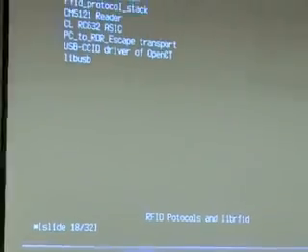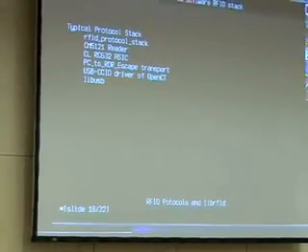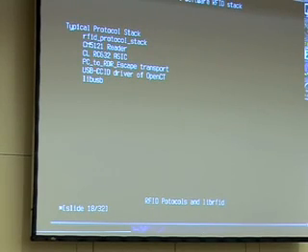So the typical stack you will have when running librfid, basically at the bottom you have libUSB that gives low-layer user space access to USB devices. On top of that you have the USB CCID driver for OpenCT, because this device here is actually a contact-based reader that you can put contact-based cards into, and also a contactless reader. The contactless card you can obviously just put here or put it in. It doesn't really matter. It just has to be closed.